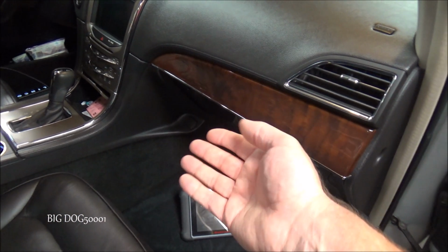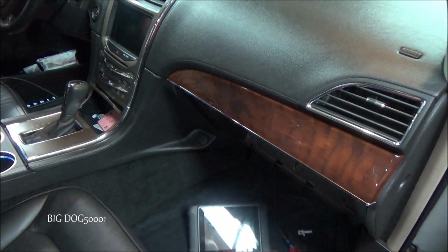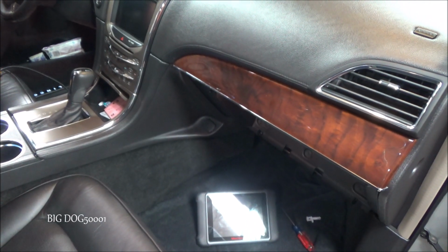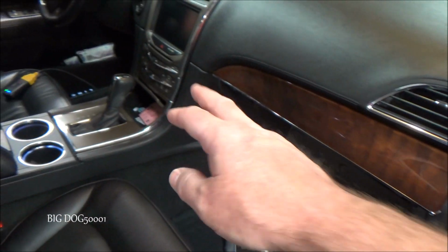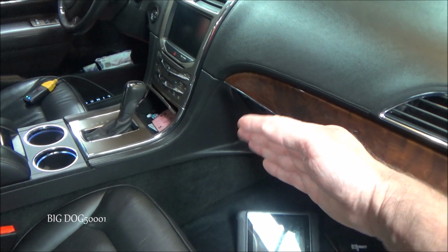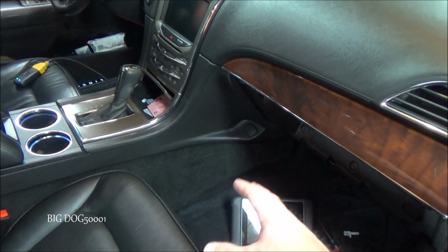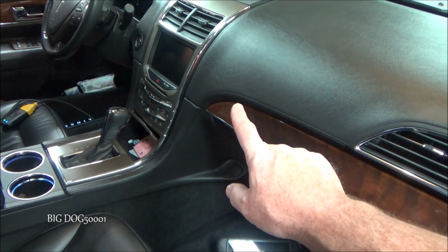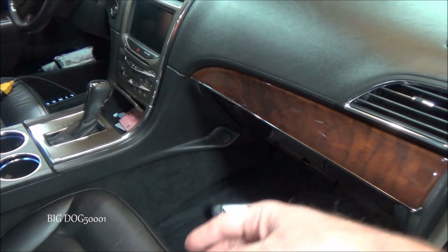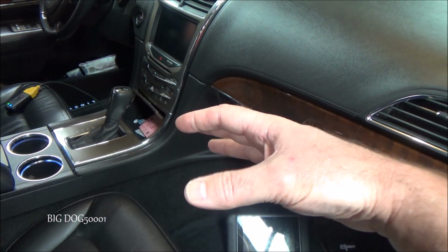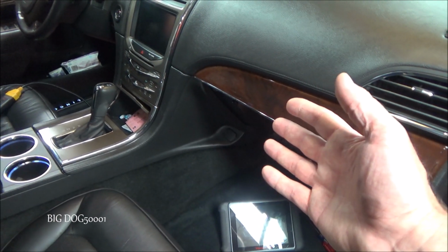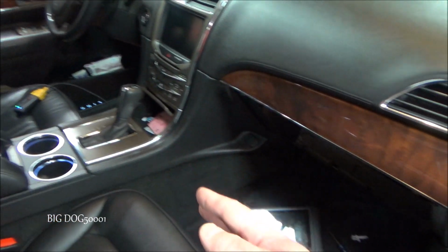Alright, so in this case, as we saw, unplugging it and plugging it back in fixed it, and it was our blend door actuator down there, or the electrical connectors at that blend door actuator motor. But a lot of times, without even taking anything apart, you can move the controls and listen very closely, and you can hear the doors and actuators moving back and forth. Especially with the vehicle off, shut the garage door or something, make everything quiet so you can hear it. If you can hear them move back and forth, then that may steer you to another issue.